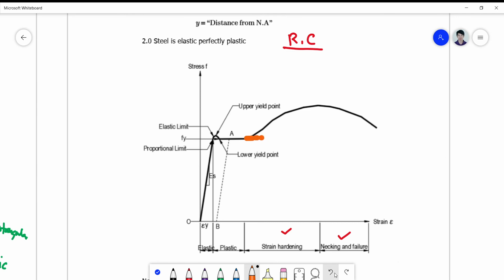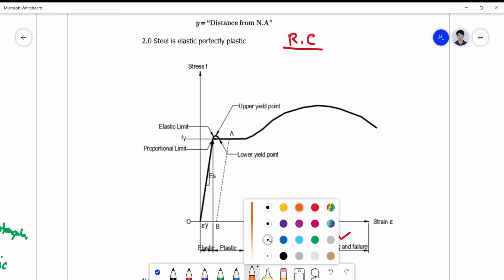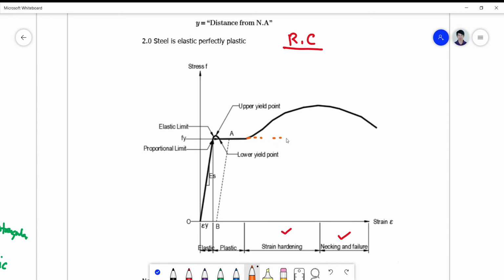So this is simply approximated in terms of a straight line that can reach a value of infinity. So this part here is no longer used, such that we will notice that your Fy cannot go beyond Fu. Okay? So in your reinforced concrete design, you still have an Fu here, but we don't use this because the assumption is only up to the plastic part. That's why if Fs is greater than Fy, we only use Fy.